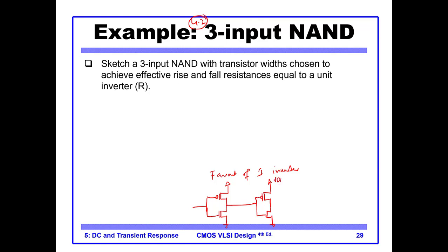So this is our VDD, this is our VN, and this is our output node Y. So this inverter was driving another single inverter, and we discussed in detail that this transistor has a size of 2, this transistor has a size of 1, and by size I mean width.